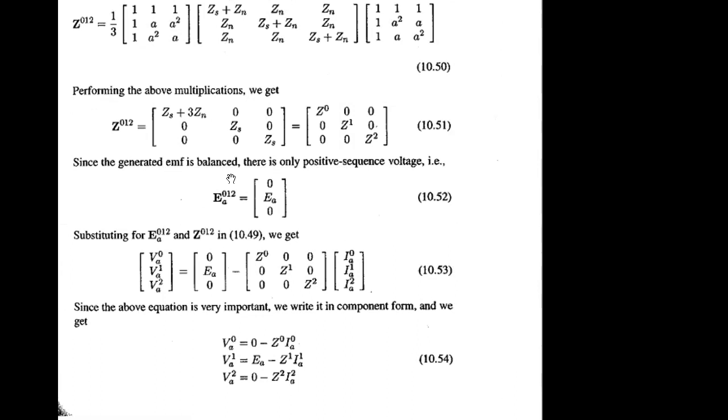And one thing I have to mention: what you have calculated up to now for the three-phase system is only for the positive sequence calculation. The circuit solution in terms of AC, which you have done in the second semester, is only considering the positive sequence scenario.